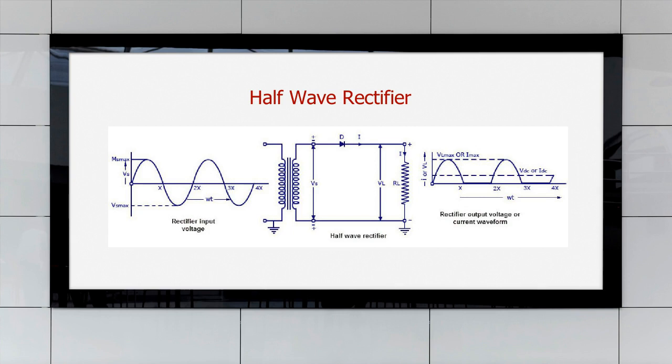So for the positive lobe, the positive pulse, it is working as a closed switch and returns the whole value as the signal, while when the negative lobe appears or negative values come, it simply goes into reverse bias, and this works as an open switch. An open switch will not allow any current to flow.